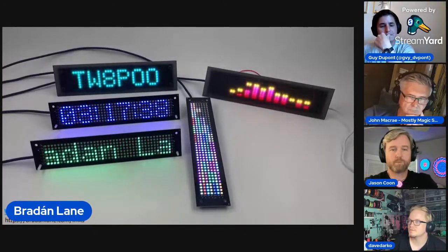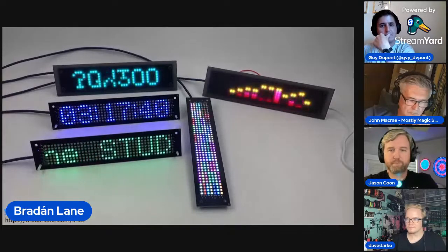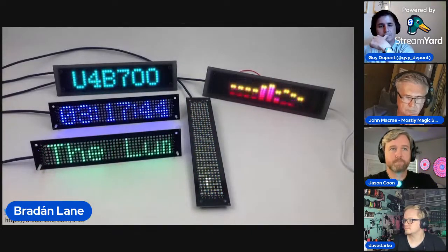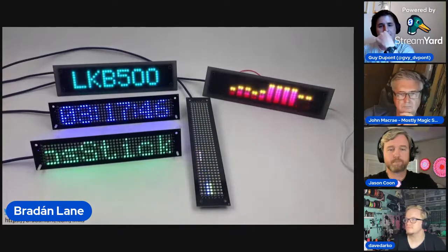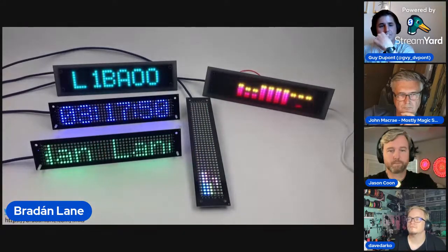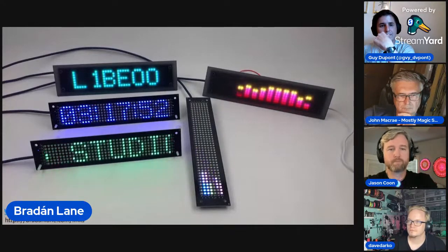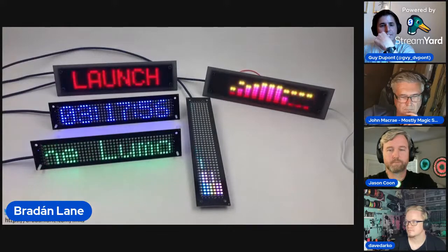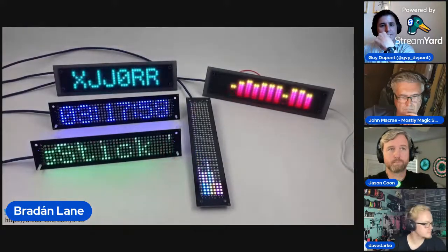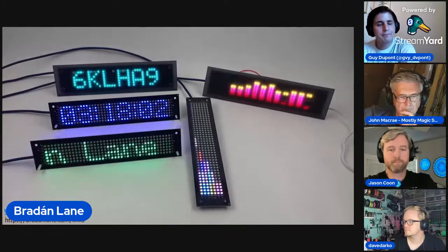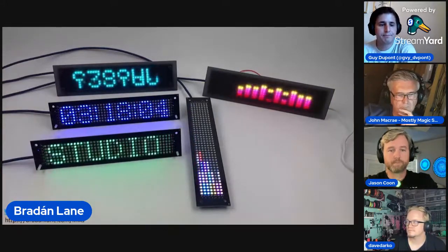Cool. And that's just using a single pin. It's not using any sort of special hardware on the back. I did try it with a microphone, and it worked, but the microphone doesn't pick up the low end very well. So that version of the demo uses a simple circuit I found, a couple of resistors and a capacitor, to take line in and feed it directly to an analog pin on an ESP32. So that's how that one's wired up.